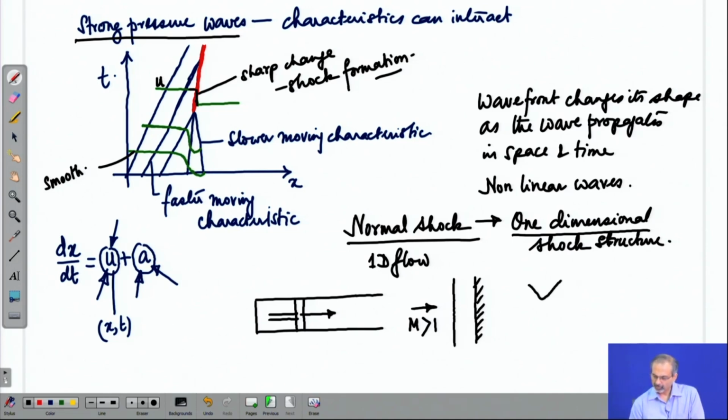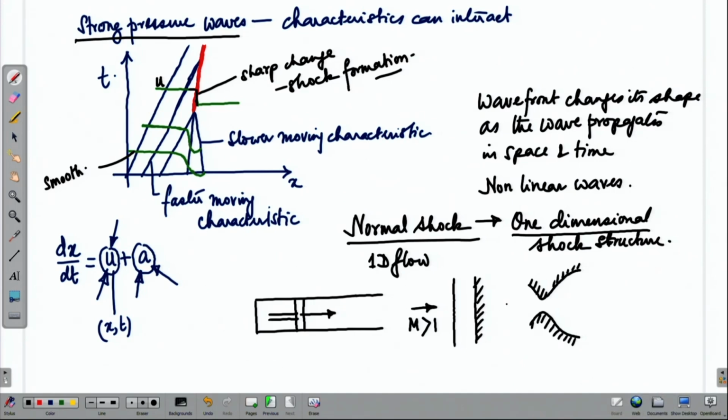If you have a flow through a converging diverging duct or a nozzle, and you are expanding a high pressure gas through this duct, if the flow accelerates from a subsonic condition to a sonic condition at the smallest cross sectional area, which we call as the throat, and then it turns supersonic beyond the throat.